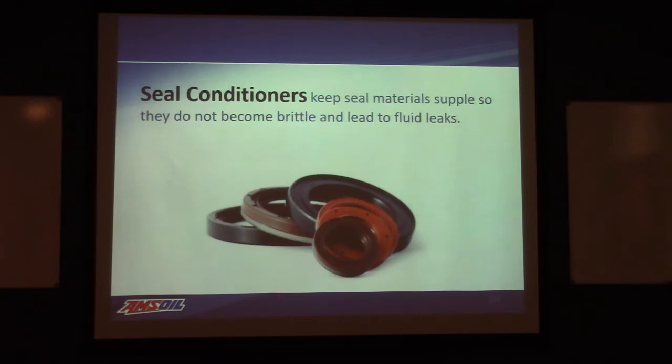But like we said, maybe a little swelling is a good thing. There are other synthetics, esters for example, that like to cause them to swell. Unfortunately, if not done properly, esters can cause too much swelling. So maybe a good combination is most of it's PAO, but throw a little ester in there. Take care of the swell situation. You get the best of both worlds.